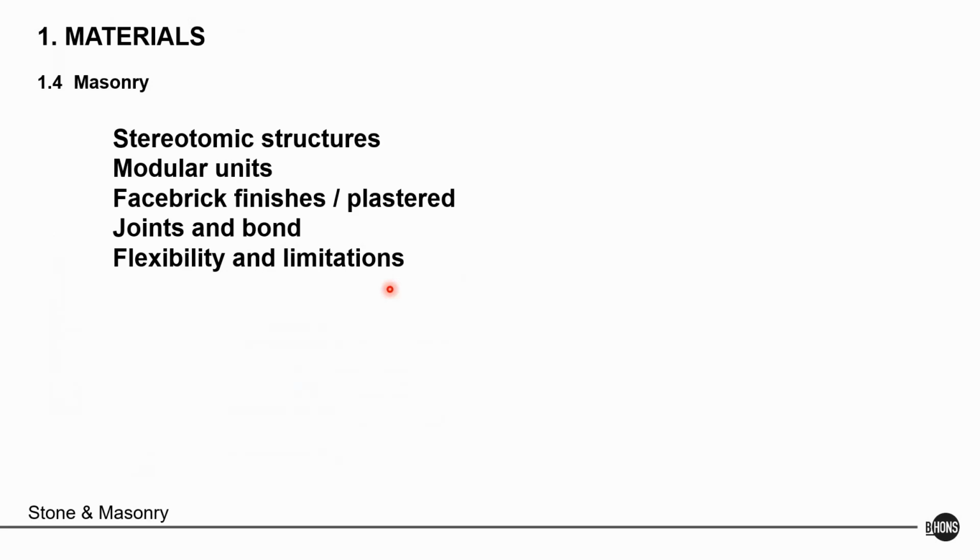It specifies that specifically. And then there's a number of ways of using buttress walls and so forth, and the thickness of the wall. So it's typically not done. Typically, you use a concrete frame structure and use masonry as infill, which I think is a more effective way to use it, but it's a bit more expensive.